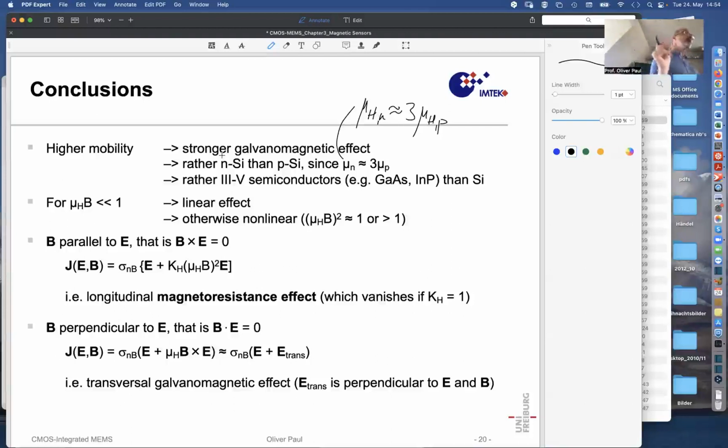But then, who can produce that sensor in large masses? Is there CMOS technology available in gallium arsenide and indium phosphide to have some circuitry to do all the nice things that we can do in silicon? Then it gets trickier. So for specialization sensors, these other III-V semiconductor sensors are fine, and there are research publications also coming out, possibly even some commercial products. But silicon prevails, at least in the mass market.